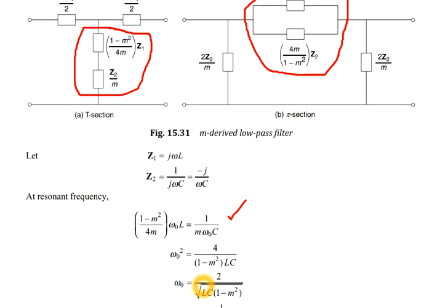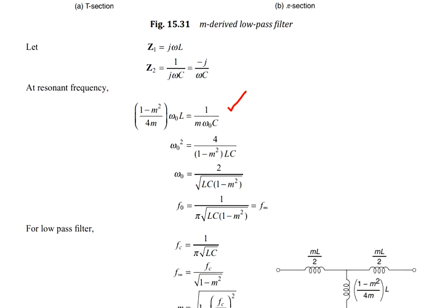So what's happening at resonant frequency? At resonant frequency attenuation is becoming infinite. So the same thing is written here. So here f infinite indicates the frequency at which the attenuation is infinite, which is nothing but the resonant frequency. That's why they are made equal to each other. Fine. So this is the expression. When you substitute 2 pi f naught, that 2 pi will be coming down. So you will be getting this simplified expression.